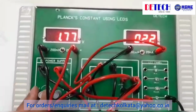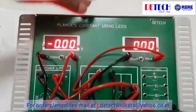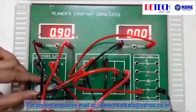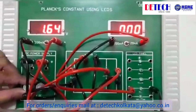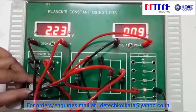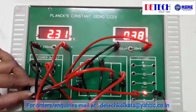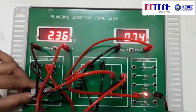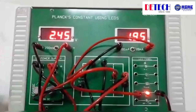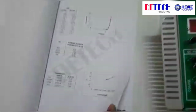So similarly, you can take the values of voltage versus current characteristics. For that, change this to the 20 milliampere range and start to increase the voltage and take down the reading for the corresponding amount of current. Initially take for very small variation of current like 0.1, 0.2, 0.5 milliampere, and then take a little bit more like 1, 1.2, 1.4, 1.5, 2 milliampere. Plot the characteristics and find out the Planck's constant from that.